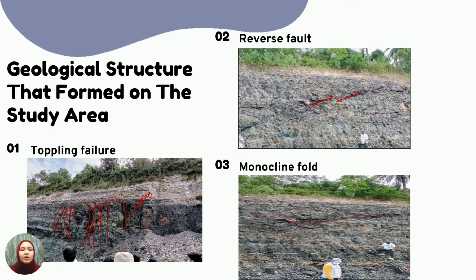When the slope rock mass features a set of steeply inclined structural planes with approximately the same strike as the slope, the rock pillar formed by the cutting structural plane may bend and the slope may undergo toppling failure. So toppling failure is a typical failure mode of rock slopes of this type.